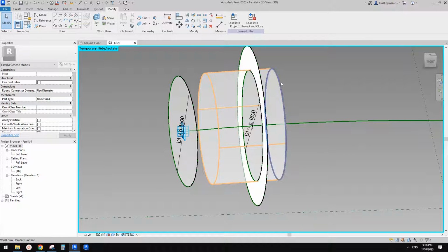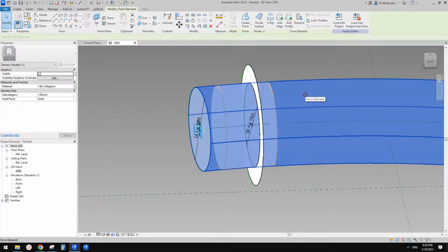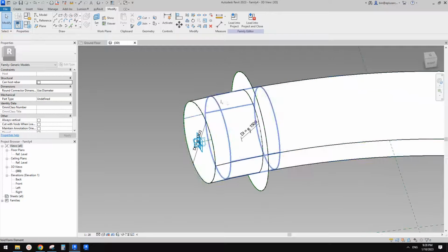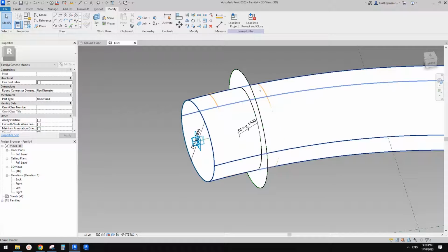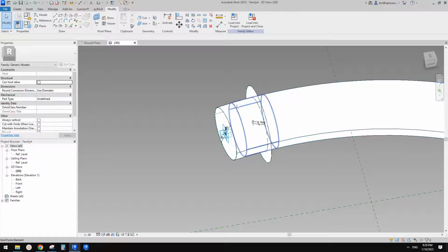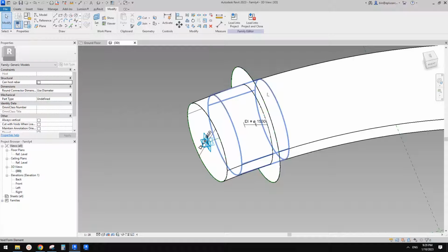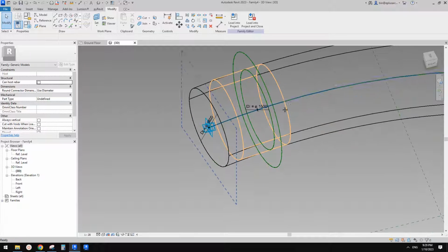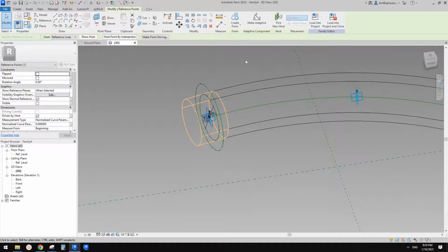Oh, looks like we have some issue here. Let me just type HR to bring back. So it looks like that's fine. It's not cutting this because the issue we usually have when we have a curved surface with a void is that you won't be able to cut. But in this case we don't want this void to cut this, so that's all good. Now let me just type WF, wireframe, and then we just need to drag this point to this end.